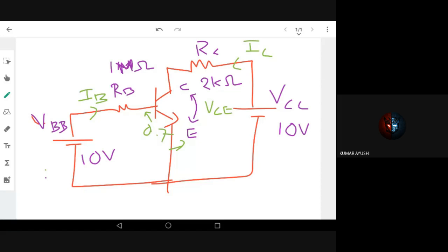Transistor amplifier is not for amplifying DC. Amplifying AC is our ultimate aim. Not AC in the sense of a signal, a micro signal, nano signal, a signal coming from a sensor. It can be nano current, nano voltage, micro current. So it is a small signal AC, or some fluctuating signal, maybe voice, maybe some light signal, any slight signal from a sensor. That is what we are trying to amplify.